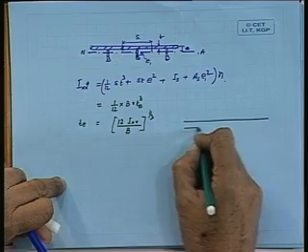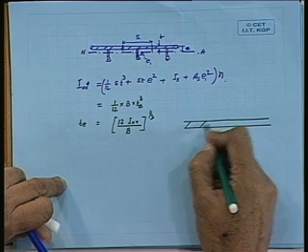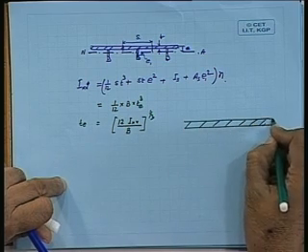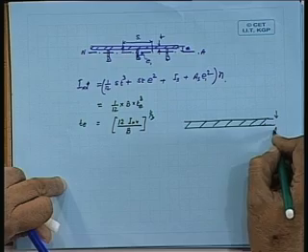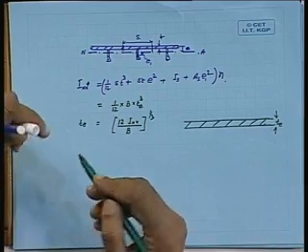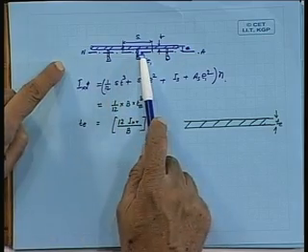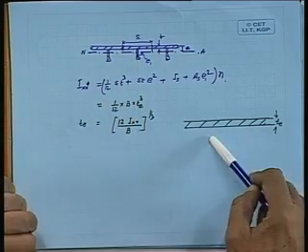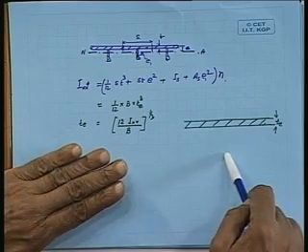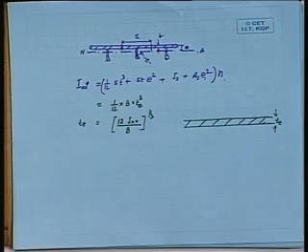So in that case I can replace this particular structure by a bare plate whose thickness is T, and this has got the same rigidity as this bulkhead plate, and then I perform a 2D analysis of this particular bulkhead plate on the basis of its end condition and the loading, and whatever moment I get, I say that this is the moment at this particular position.